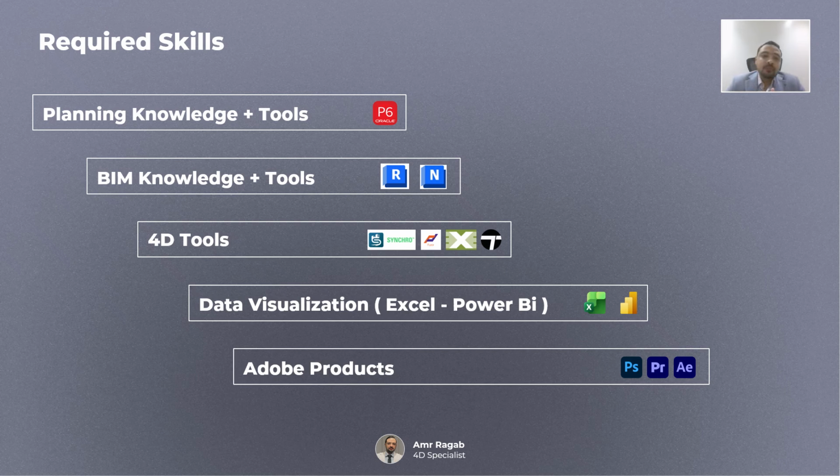So next you move to BIM tools and modeling, focusing on Revit for model creation and Navisworks. There are two options. The clients can give you native files in Revit, or they can give you NWD, NWC, or NWF files, and you can handle them. There are many plugins you can use to export your model. If you know these plugins, it will be easy. But you need to learn Revit, or at least know the internal process of coding inside Revit: how to add or copy parameters from the Excel sheet to the right elements.